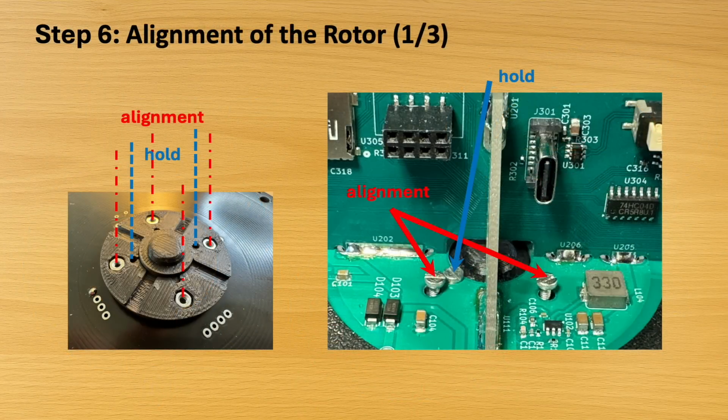Now comes a very critical step, aligning the rotor relative to the axis of rotation. I have to admit I initially underestimated the importance of this part. Precise work here is essential, both to ensure smooth operation without imbalance and to accurately align the LEDs for the interlacing pattern. The photo shows the mounting plate on the motor shaft.